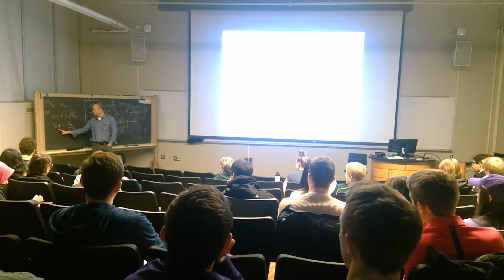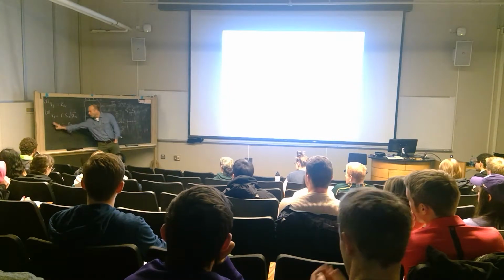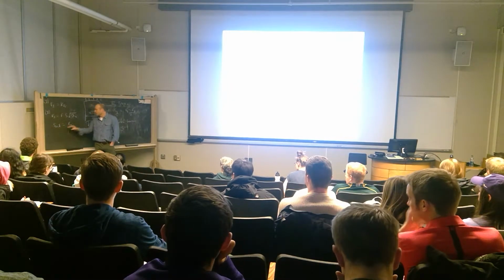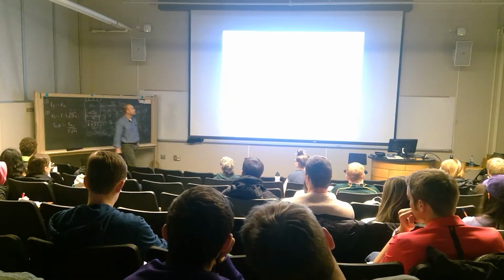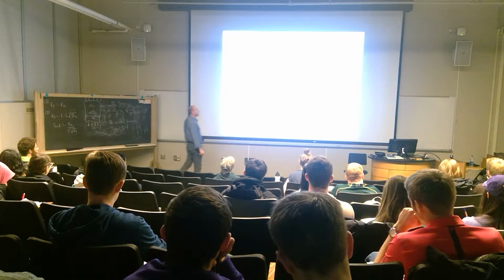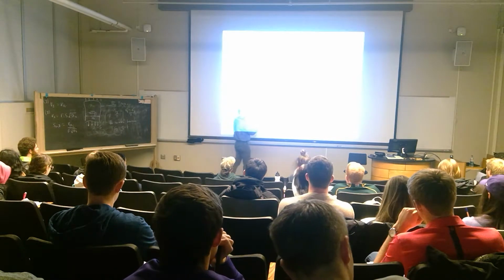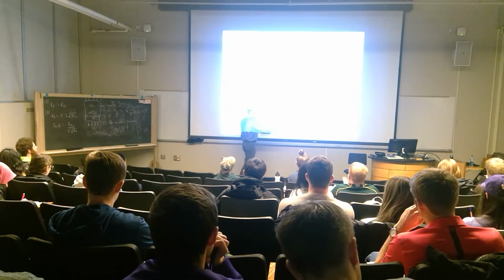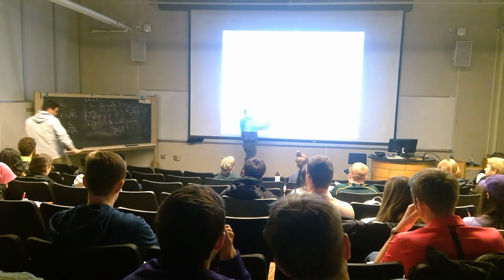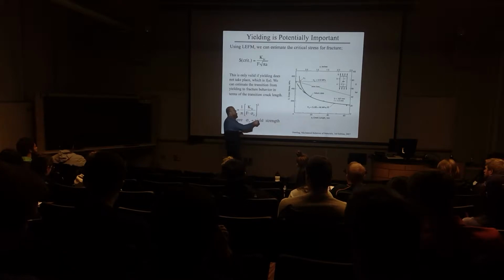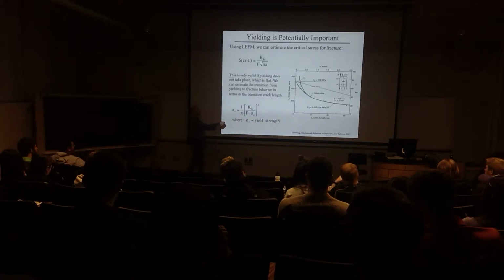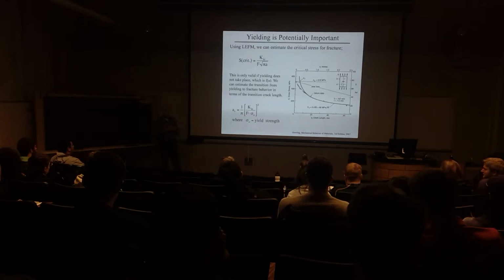And so what we like to do is think that we can talk about the critical stress in our structure for a choice of fracture toughness in terms of the distribution of flaw lengths. And here is what's in your notes then to describe that behavior. So we see as the crack becomes smaller and smaller and smaller, that what happens actually is that the critical stress for fracture to take place is increasing. But we know that that's not necessarily boundless because no structure can withstand or resist an infinitely high stress.